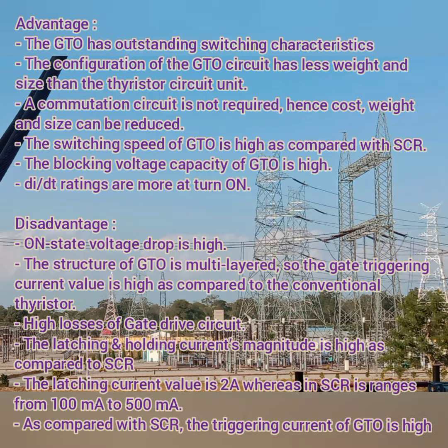Then the structure of the GTO is multi-layered, so the gate triggering current value is high as compared to the conventional thyristors. High loss in gate drive circuits. Then the latching and the holding current magnitude is high as compared with the SCRs. Then the triggering current of the GTO is very much higher than the SCR.